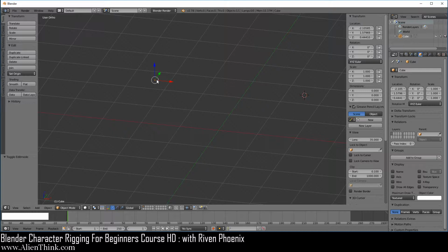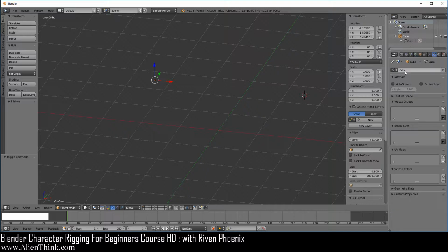Go ahead and now click on object mode. Notice that we can still access the object, meaning that the vertices that define what this object looks like are a separate concept. And you can see this by clicking this open and looking at its data block. The vertices, faces, and edges that define what your 3D model looks like are kept in this data block. You can actually click on this tab to see the name of it here. So the data block is simply linked to this object.